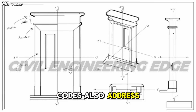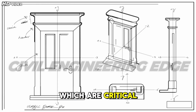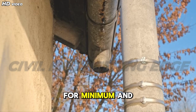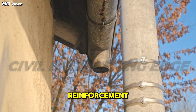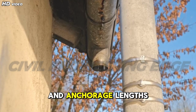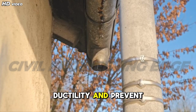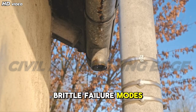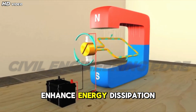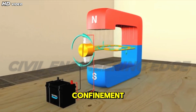Codes also address detailing requirements, which are critical for column performance. Specifications for minimum and maximum reinforcement, spacing of lateral ties, concrete cover, and anchorage lengths ensure ductility and prevent brittle failure modes. In seismic zones, additional provisions enhance energy dissipation and confinement.